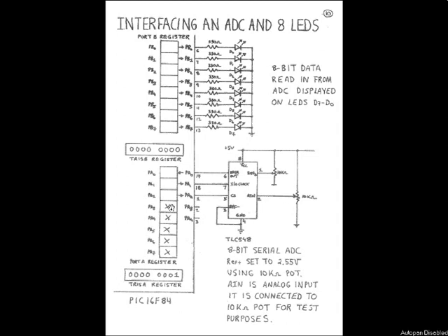In this particular case, I'm not going to use PA3, PA4, PA5, PA6 and PA7. I've just crossed them out, or put an X or don't care, in those locations inside the port A register. They're not used in this application. I'm only using 3 of the port A lines. I could use the other 2 lines for something else if I wished, but in this simple application I'm not. To get the port A register to work properly, I need to load the following 8-bit value into the tris A register: 0000 0001, which is hexadecimal 01, or the number 1 if you like. So the tris A register has to be loaded with that value.